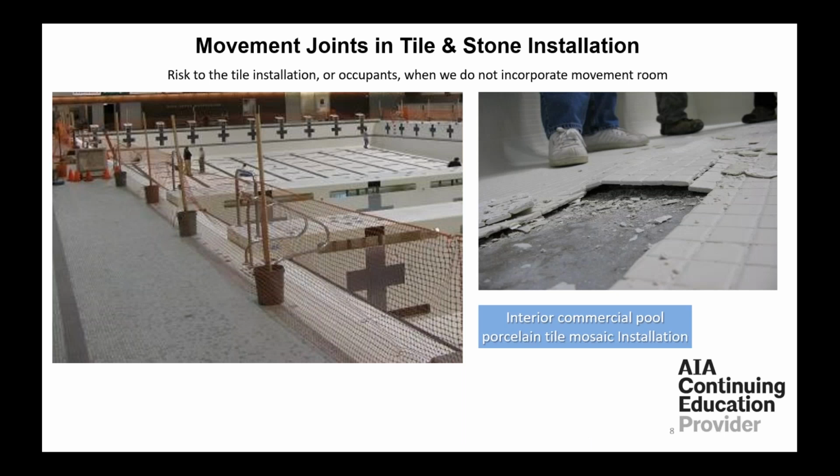This is a pool. Unfortunately, it failed. And again, I've seen many of these. I had a pool over in Hilo, Hawaii, and it just sat in 8 inches of rain almost the whole time. Failed miserably, but that's not this pool. But this one, when they did take out the grout, the tiles just laid down fine. So then they put the movement joints in and reinstalled the tile and regrouted.